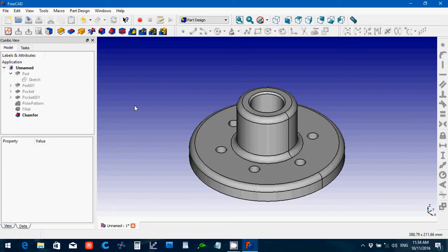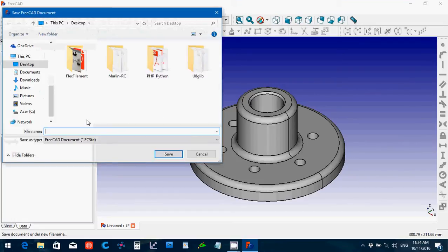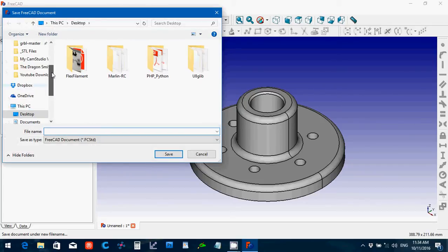It's just a bit annoying that changing the parameters then changes the actual object. So that's the first flange, and I'm just going to save. Now I probably wouldn't actually 3D print that unless I absolutely had to, but this is just to show that you can go in, use books that are on other topics, and then try to convert them here in FreeCAD.